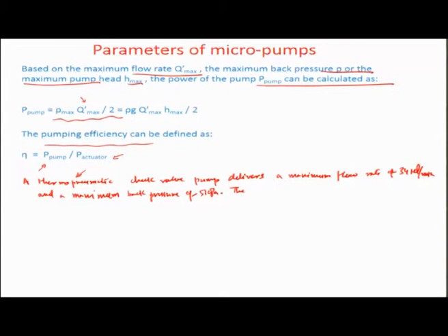We have already seen this while designing the static valve example in one of the lectures. So, here we are actuating a heater with a certain resistance to go up to a certain temperature, so that it heats up a hermetically sealed cylinder with, let us say, an air confinement, and the air expands because of Charles's law and creates a membrane deflection.